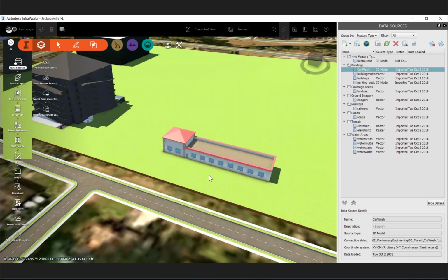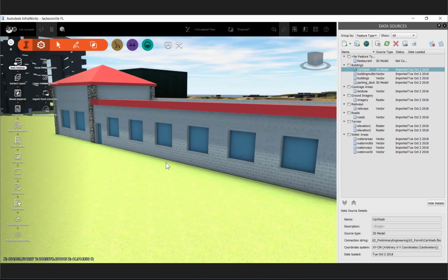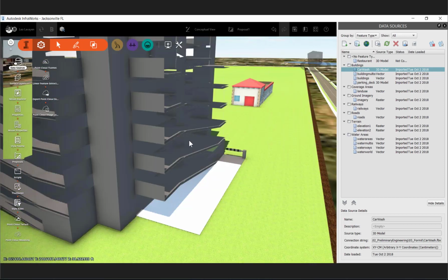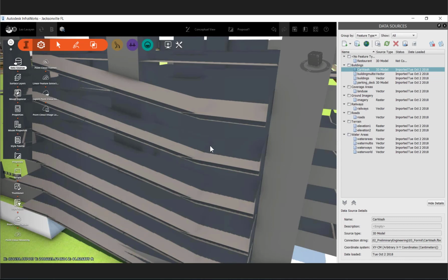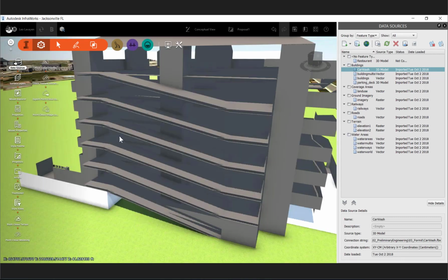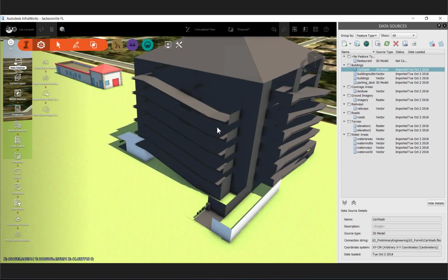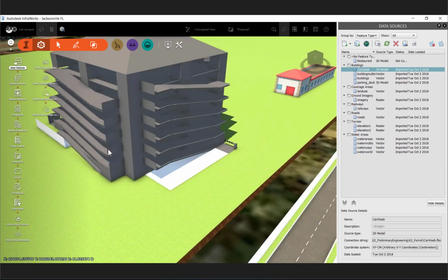And it does the best it can to bring in materials. Notice how this particular Autodesk application, as it spit out that FBX file, did bring in materials for me, whereas this SketchUp file didn't bring in the materials as it should have. So I'm at the mercy of what is able to come on over, and whether or not I have those source files. A lot of times it's a matter of taking their images and their materials and placing them inside of the same folder that this particular file sits in, and then boom, images and materials come right on over.